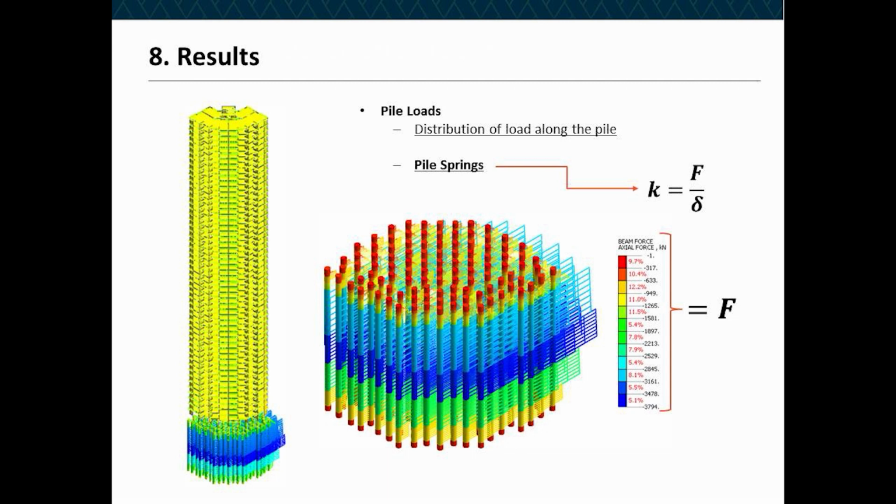Those springs are different for each pile, and this might be understood by us and by our structural colleagues. The reason for this is mainly the position of the pile inside the raft, which can be affected by the location of a column. We may understand this as a more or less loaded region, or due to pile group effects, which tend to decrease the performance of the pile, meaning that some may not offer the same reaction as others.